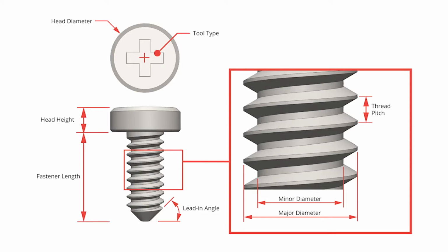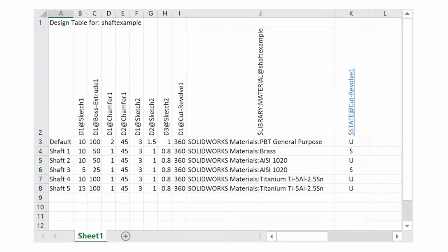How would that work? For a screw, for example, we would create a generic parametric screw, one of generic length, generic girth, generic threads, generic head type. And then in a design table, we could specify a number of parameters that would allow us to just basically click one button and get the new screw. Now, the key behind design tables is that design tables are executed, or I should say maybe created, in a spreadsheet-like format. And that spreadsheet-like format is what you're going to learn in this chapter, and you're going to practice it.